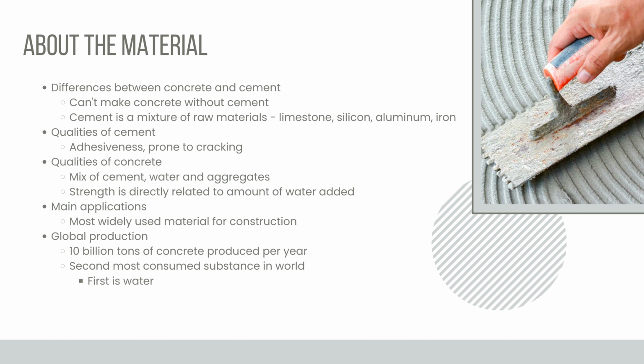However, when cement is mixed with water, it creates a paste. And then once aggregates like sand, stone, rocks, gravel, etc. are added to the mix, that is when it then becomes concrete. This process is an exothermic reaction and is called the heat of hydration because heat actually emanates from the concrete during this process. The generic ratio for concrete is usually 1 part cement, 2 parts sand, and 3 parts aggregate.